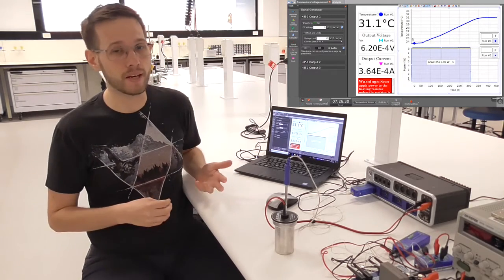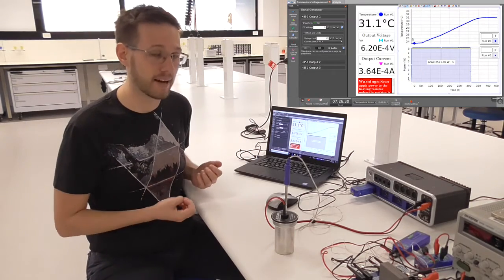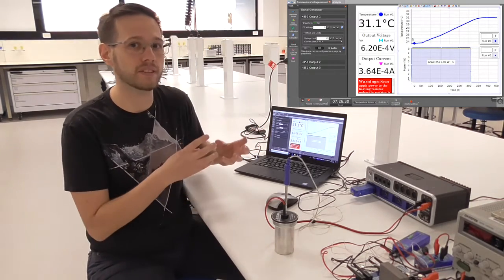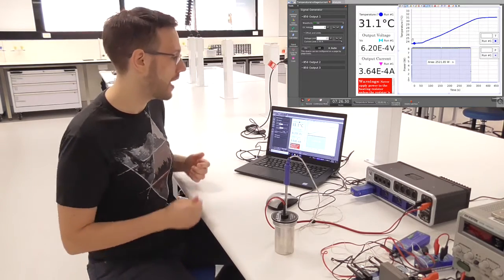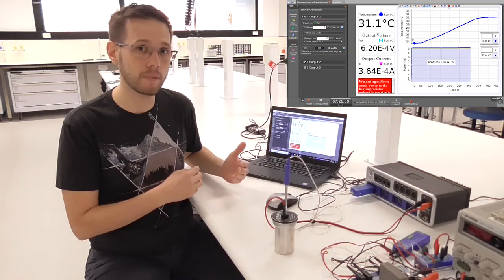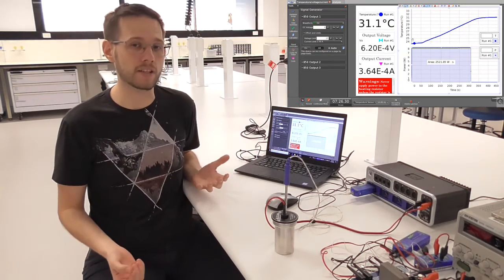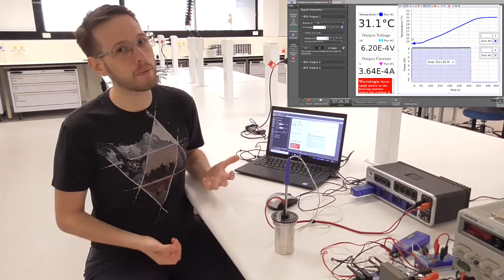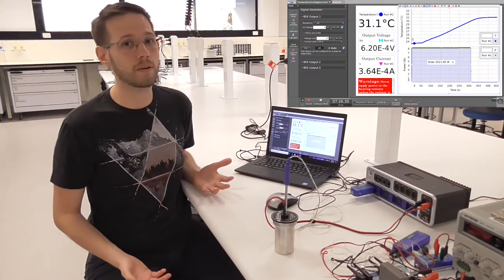We just need to remember the ratio of the masses, so however much mass the aluminium was and however much mass the water was, and then we combine those together into two terms, which you'll see done earlier in the lab manual. We combine that together to work out how much heat energy that we see in the system, and then in the last part of the analysis we can compare that with the amount of electrical energy we put into the system to see what the efficiency of our heating element in there was. And that's how you do ET1 Part B.